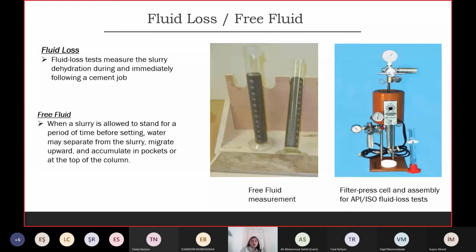But if you have a liner job, a very critical job, you are in the formation area, you will get less fluid loss. And we add a fluid loss control additive. Without it you are getting high fluid loss, 200, 300, 350, 400 milliliters.